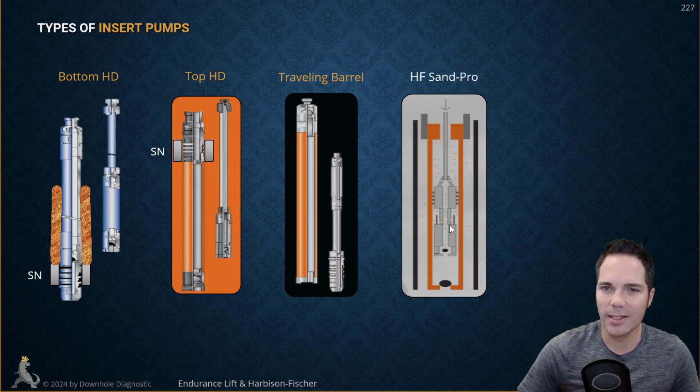And then also it's got this lower pressure sealing plunger. So this is the sand handling plunger, the pressure sealing plunger. Basically this plunger right here is just trying to wipe everything clean and prevent any solids from getting down between this plunger and the barrel right here. That's what it's trying to do.